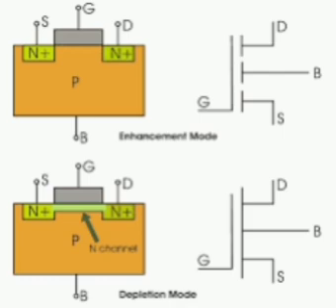Field effect transistors. FET is a voltage controlled device. It is a high impedance device. It is a majority carrier device. It is less noisy than BJT. It is thermally stable. It is smaller in size compared to BJT. Leakage currents are zero. It is a unipolar device.